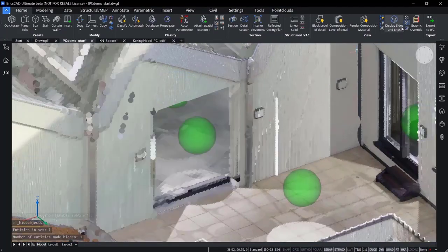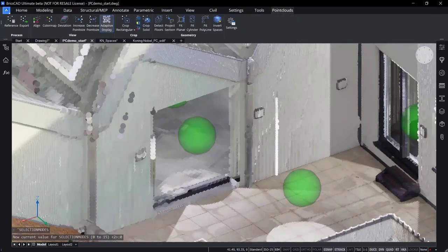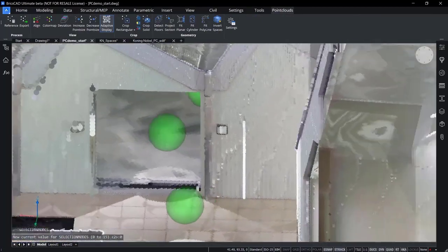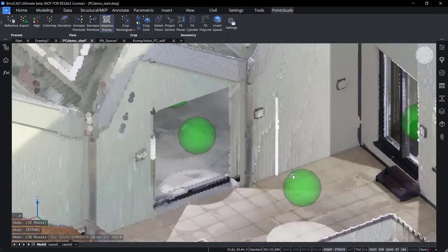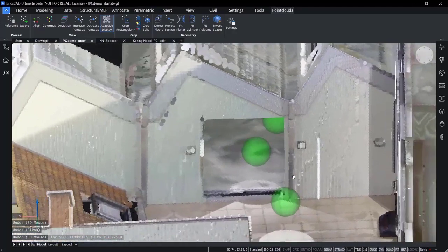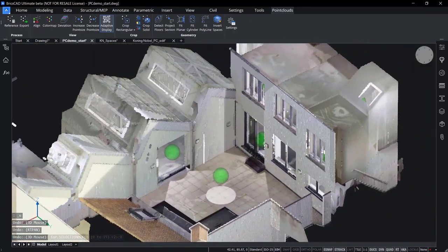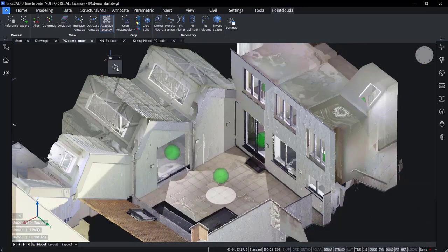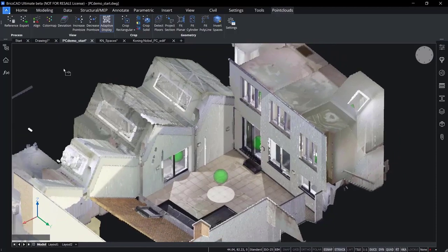So like that you have your full point cloud, but you will have some things deleted or the implementations done that you want to create, to see if it works and to see how it looks. So like this, you can edit your point cloud and delete some parts out, very specific parts. The same way, you can just unhide or show it back again, and you will have your solid, and if you delete your solid, you will still have your full point cloud.